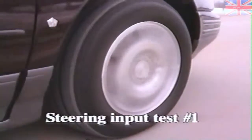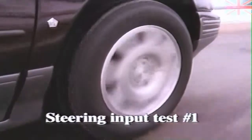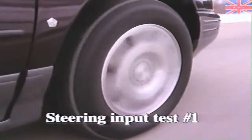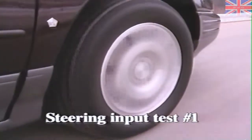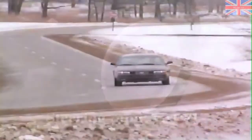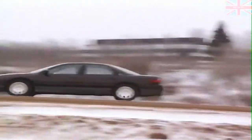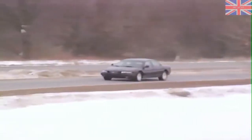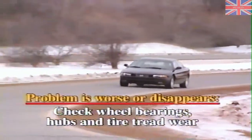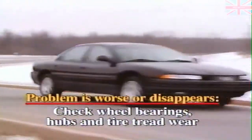The first steering input test is intended to determine how much wheel bearings and other suspension components contribute to an existing vehicle speed-related noise or vibration, especially those relating to noises like howl or growl, grinding, and roaring. With the vehicle at the vibration speed, drive through sweeping turns, first in one direction, then in the other. If the existing noise gets worse or goes away, worn wheel bearings, worn hubs, and abnormal or excessive tire tread wear are all possible causes.